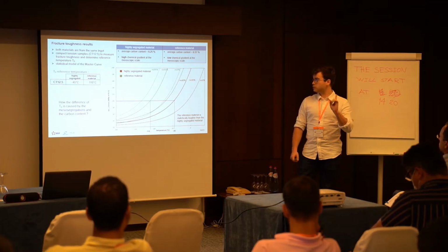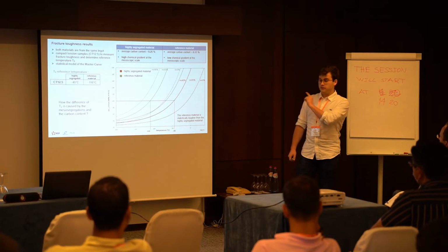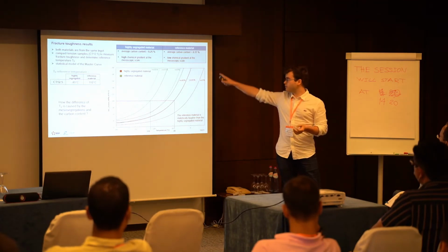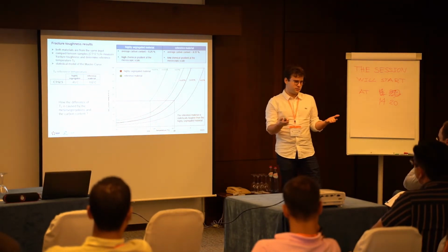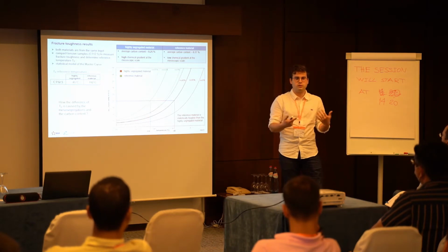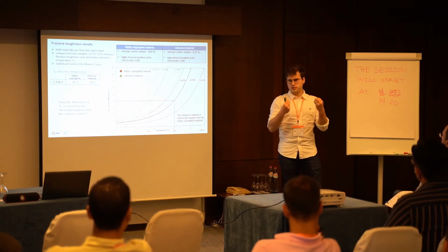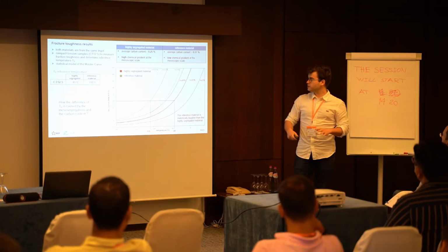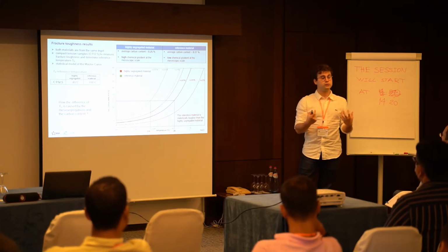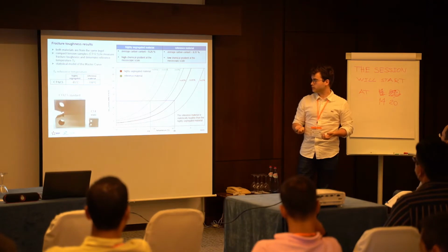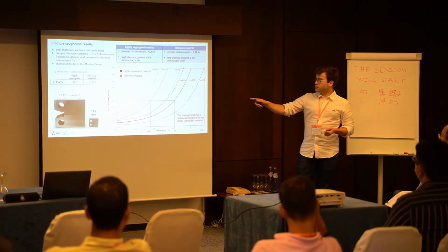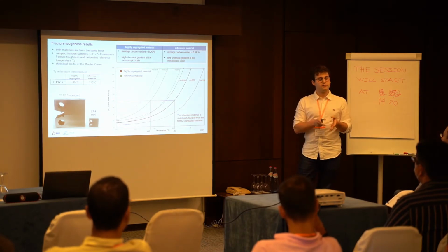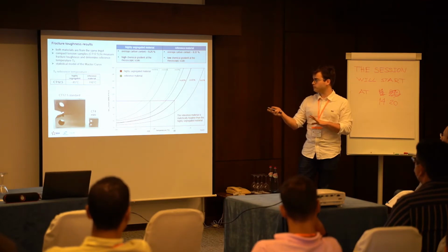However, this is important: at this point, we cannot say that this difference of mechanical behavior is only due to the heterogeneities, because the average carbon content is very different, and carbon content plays a major role in fracture toughness properties. So to only study the effects of meso-segregation on fracture toughness properties, we did the same experiment but with reduced size samples. Here they are. The mini samples have a thickness of 4 millimeters instead of 12.5.